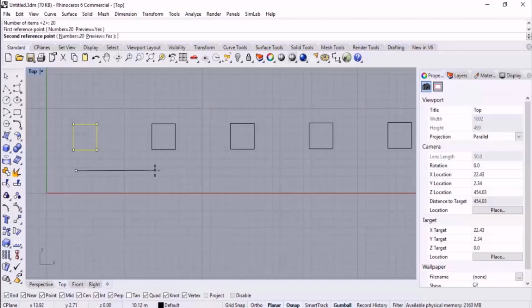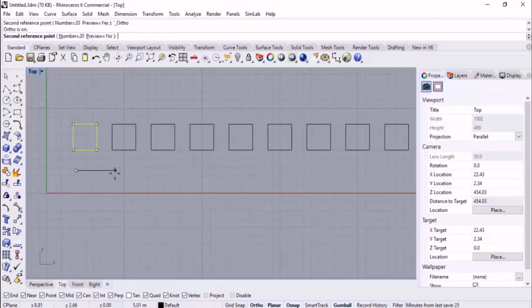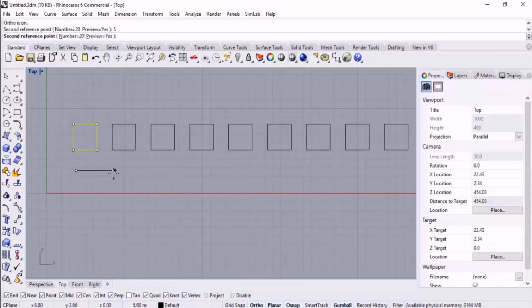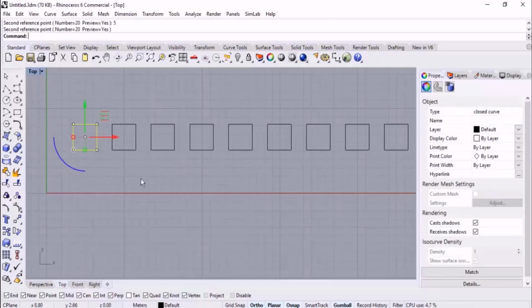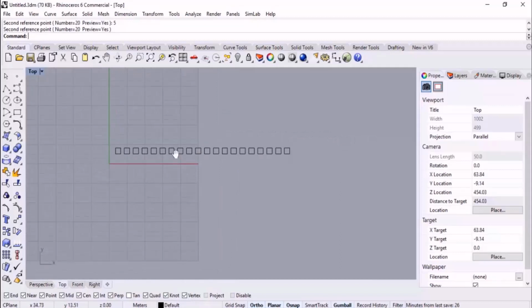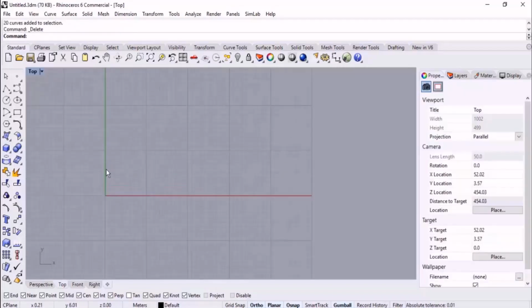You can use the commands for sketching lines to consider angles or fixed lengths. For example, I press F8 to activate ortho. Then I specify 5 units, enter, and then I specify the direction, and I click to finish the array. As I told you before, when you are using commands like move, copy, and also array, you should activate project and planar in the 2D views.